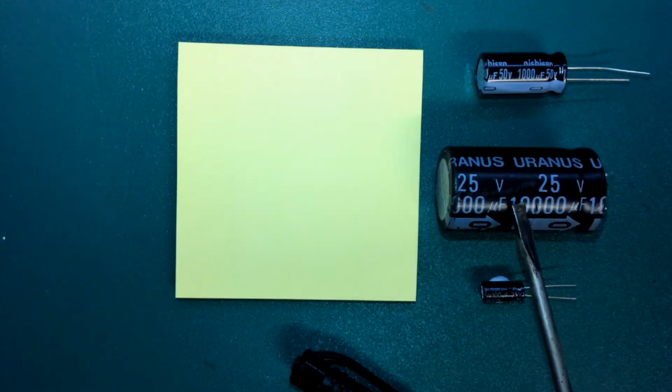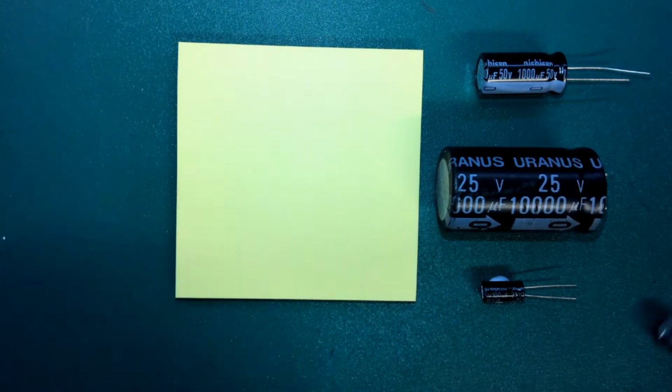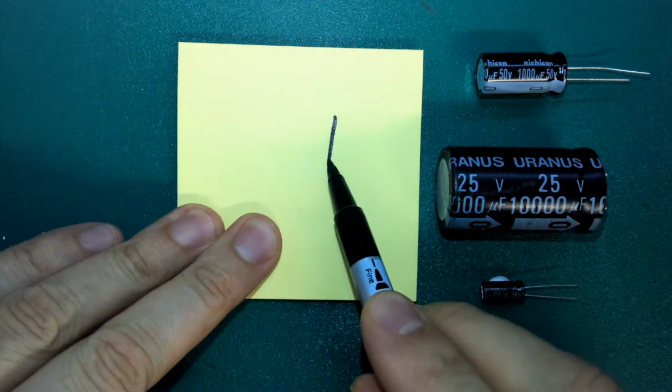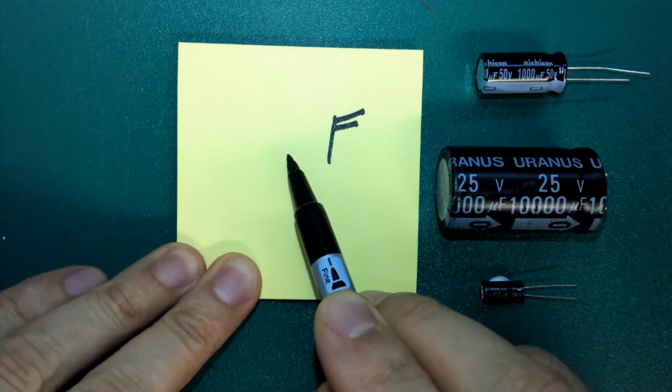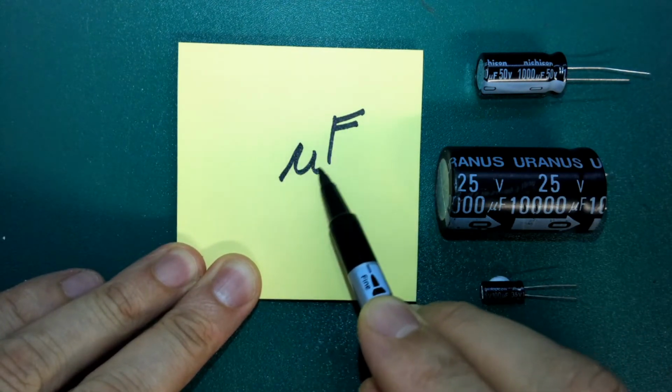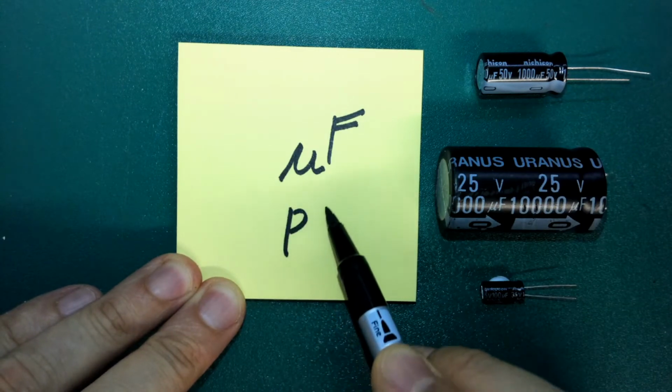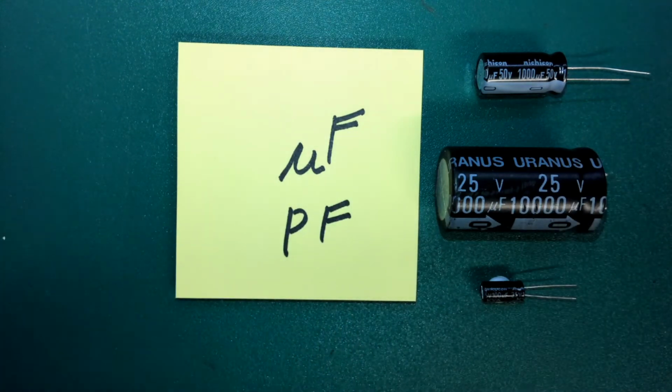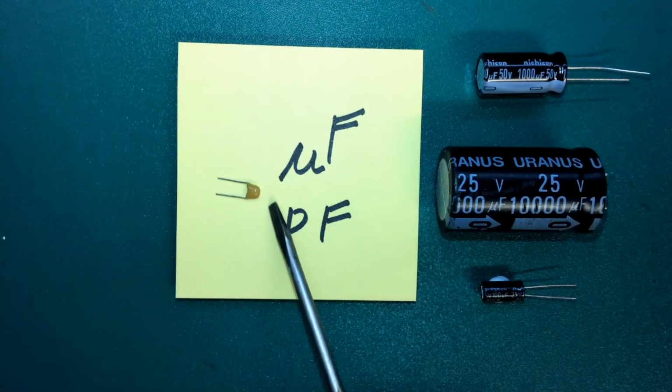A capacitor's electrical size is measured in farads, and that's written like this. It uses an F or a UF or a PF. The F stands for farads, the UF stands for microfarads, and the PF stands for picofarads. A 1 farad capacitor is really a large capacitor, so it's quite normal to use a value between 0.1 of a microfarad and 500 microfarads. But sometimes you might want to use these really tiny capacitors, these picofarad capacitors. And this is a very small value of capacitance.